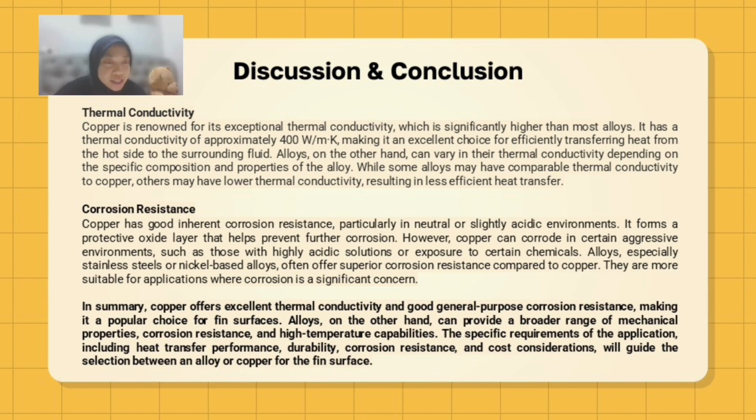Next, the conclusion for this assignment. In summary, copper offers excellent thermal conductivity and good general-purpose corrosion resistance, making it a popular choice for fin surfaces. Alloys, on the other hand, can provide a broader range of mechanical properties, corrosion resistance, and high temperature capabilities. The specific requirements of the application, including heat transfer performance, durability, corrosion resistance, and cost considerations, will guide the selection between an alloy or copper for the fin surface.